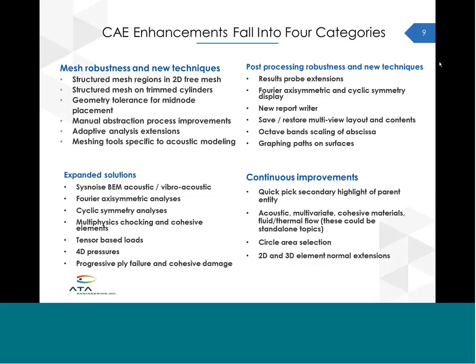There's additional controls to give you additional tolerance for mid-side node placement, greater control for manual abstraction if the mesh doesn't come out quite the way you want, a number of enhancements to adaptive analysis, as well as a number of meshing tools that are specific to acoustic modeling, if that's something that you're interested in. Another category is expanded solutions.